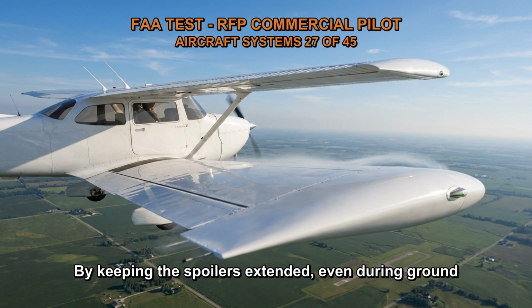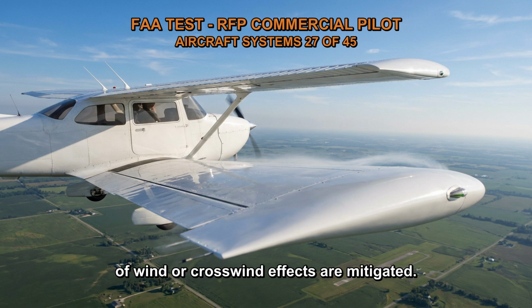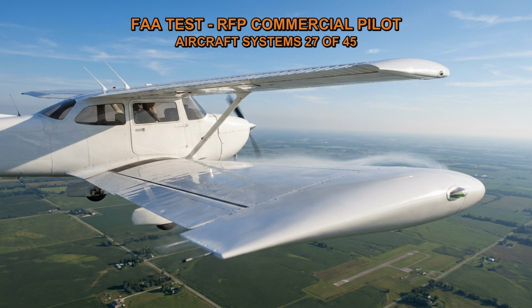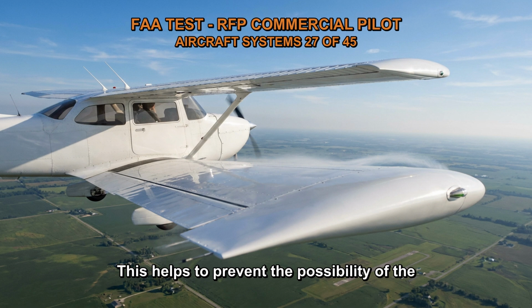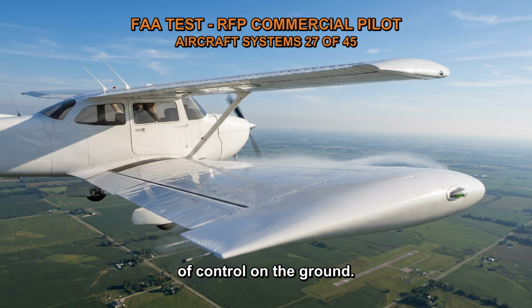By keeping the spoilers extended, even during ground operations, the pilot ensures that any sudden gusts of wind or crosswind effects are mitigated. This helps to prevent the possibility of the aircraft becoming airborne unintentionally or experiencing a loss of control on the ground.